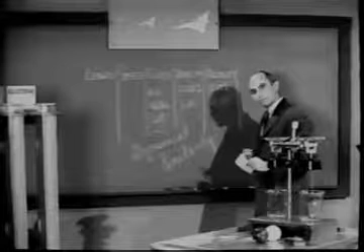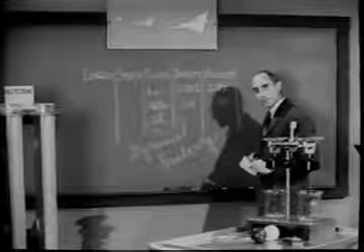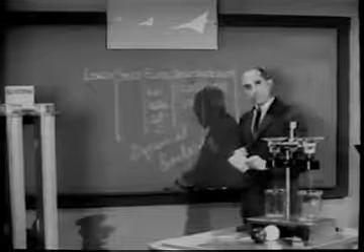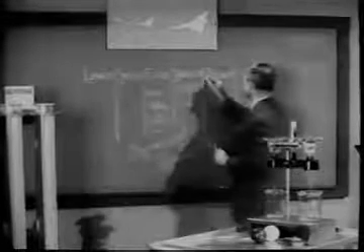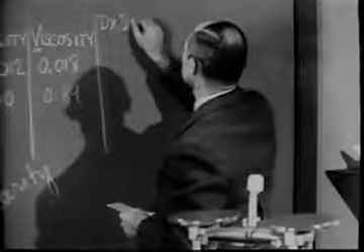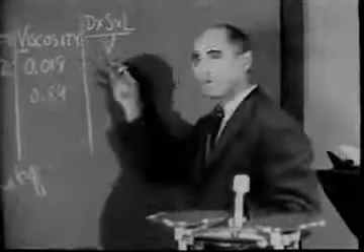That combination is the density times the speed times the length, all divided by the viscosity. This ratio is called the Reynolds number, after the engineer-scientist Osborne Reynolds, who gave us the first clue to this idea about 80 years ago.